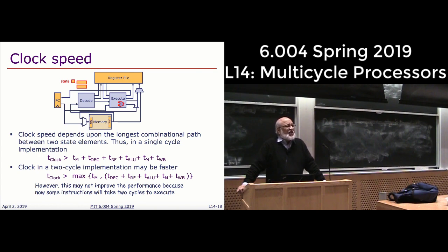But the problem now is when it comes to throughput, we haven't really won, right? Most instructions will get done quickly, but the memory instructions will take twice as long. So you say, oh, I will win with this new clock, provided the number of loads and stores is not larger than something. It's becoming a slightly more complex calculation. And as we do more sophisticated designs of the memory, these kinds of questions get harder and harder to answer.